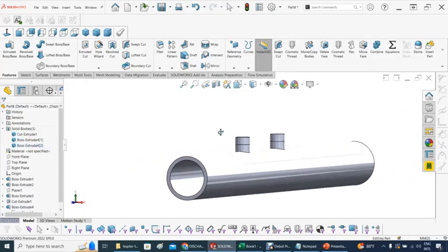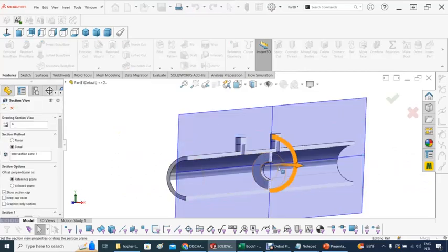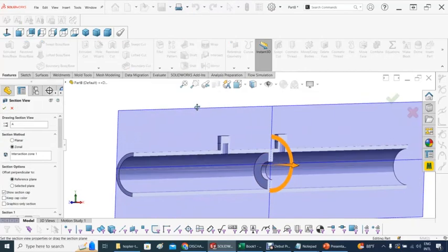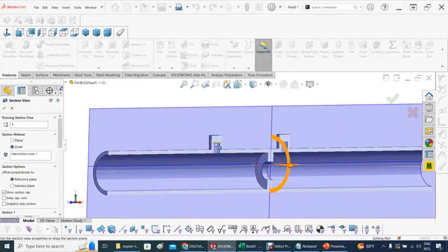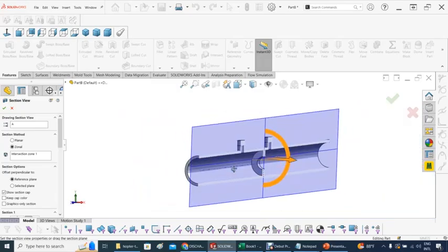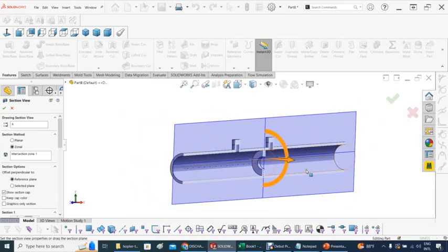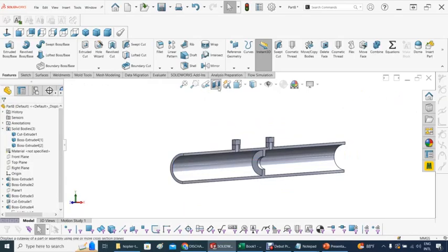Now it's perfect. And let's take a look how this starts to look. You can see that there's a seal right there, and the idea is to locate in the flow simulation a pressure. You're gonna install there something to measure the pressure at that point and the pressure here, so you can get a nice delta P for your flow simulation. As if you are designing an orifice kind of flow measurement device. So let's say that we accept this and we add it here.